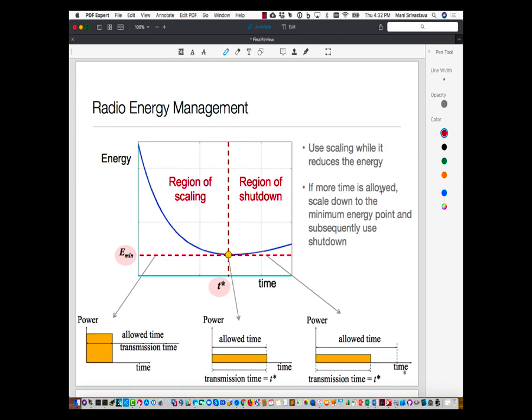And this is something that you encounter quite a bit in radio standards around us, like Wi-Fi, for example, or cellular. They routinely switch the data rate at which they are transmitting. So many a time you are better off in terms of effective energy per bit. Let me clarify that. Let's say I'm sending the data to a particular node, and there is a probability that bit loss will happen. So let's say my radio link is nominally a megabit per second.